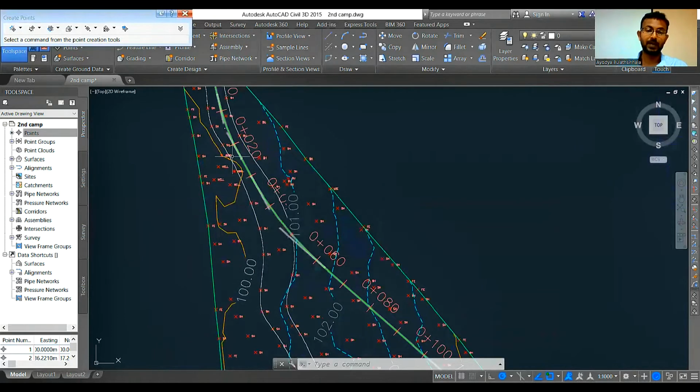Because these are not exact points. These heights are generated by the contour map, right? That height may actually be there, but most of the time this height is not there in the actual place, right? That's why we need to get the heights again after doing the setting out. So now I need to get these points to a table. So this is how it is done.